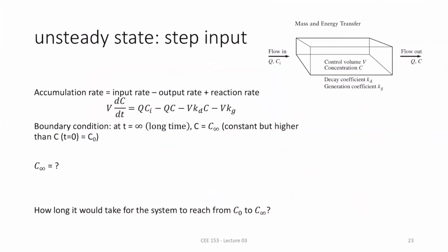What if that same thing, that you are blowing air, but that air has a lot of pollutants? So that means the concentration of contaminant in the home will increase, because now you are blowing not just clean air, you are blowing way higher concentration than you thought. So if that happened, how long will it take before you realize that there is a steady state, meaning the concentration will increase and it will remain at a certain point? So you want to know that.